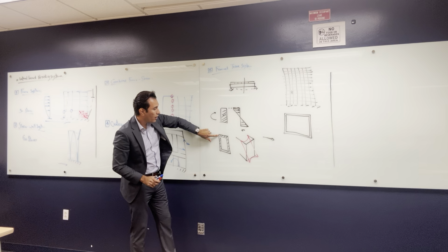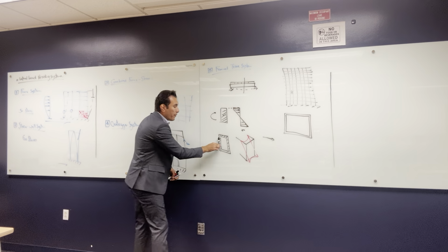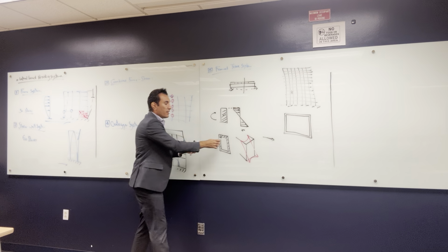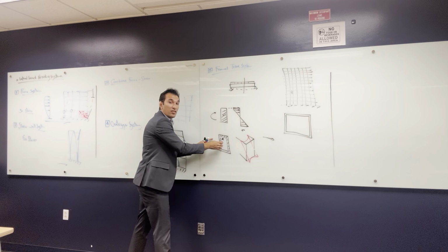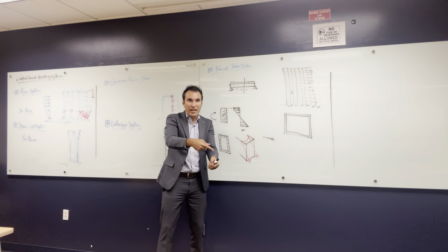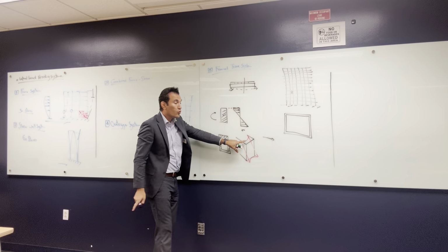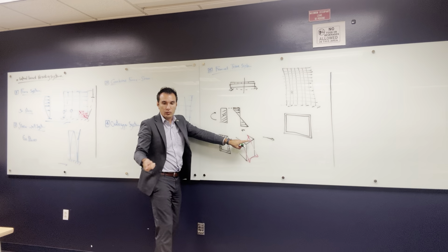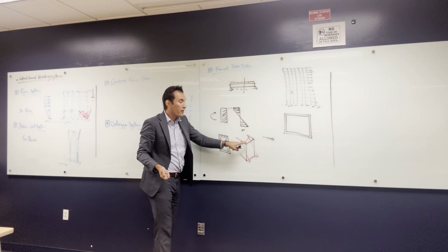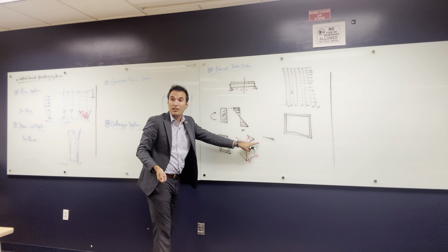This section has a web that is pulling this section up, and at the same time from the other hand, but this part is weak, it doesn't have something to back it up from here. So it's like somebody's pulling from here and somebody's pulling from here, and in the middle nobody's pulling the other section. So they are gonna try to pull it, like they are trying to stress the other parts, but not as much as on the corners. So there is a stress concentration at the corners.